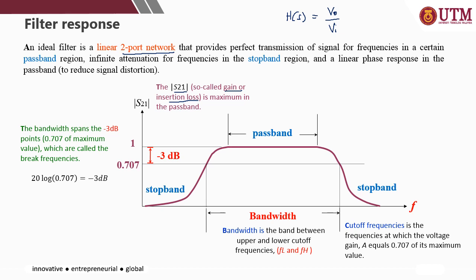Alright, so the value on the y-axis here is the linear value, and if it is in dB, it is 0 dB or negative 3 dB. Negative 3 dB is where the power has been reduced by at least 50%. The bandwidth is measured across the 3 dB lines. So for example, here is f1 and here is f2. So the bandwidth is basically f2 minus f1.